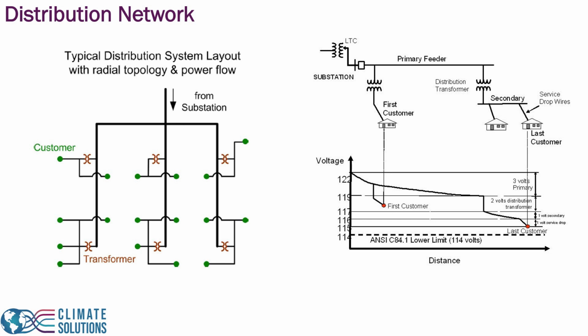Now, the final issue is that congestion also happens in distribution networks. But unlike transmission networks, where congestion happens at the transmission lines, in distribution networks, congestion typically happens at the transformers. When there is a lot of power demanded by the consumers, that power will be limited by how much power can flow through a transformer. This is why, for example, we will see later that when you add technologies such as electric vehicles that significantly increase the power demand, we may be required to replace these transformers.